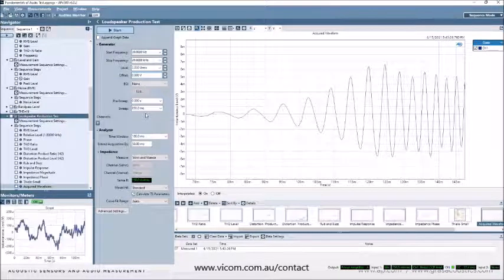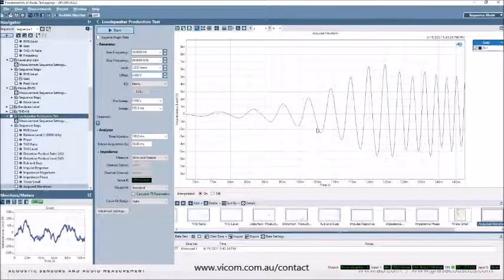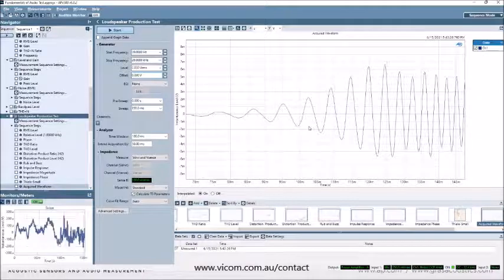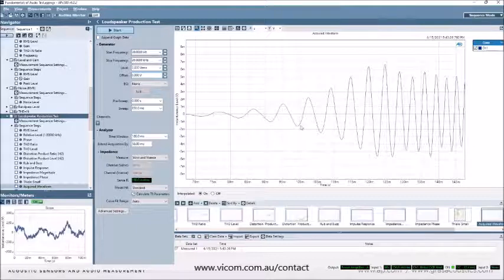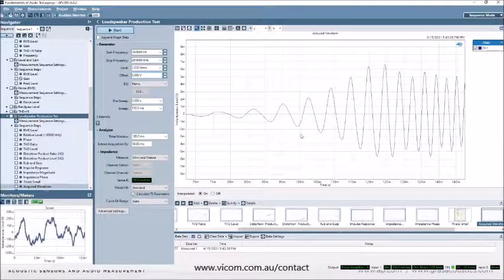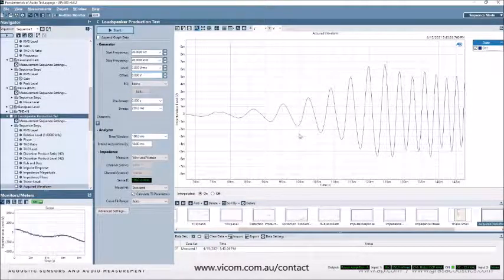In a log chirp or an exponential sine sweep, or sometimes it's called a Farina sweep, the frequency of the test signal is continuously changing. There's no 2 seconds or 1 second or even any 2 audio samples that have the same frequency. And the frequency is increasing. So it starts at low frequency and ends at high frequency.